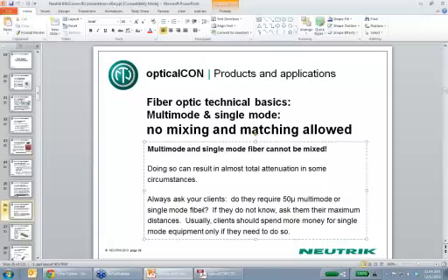Is there any hope of MADI equipment migrating from multimode to single mode in the future? Oh, this is a great question. All right, so let me talk quickly about MADI. This question came from an audio person. The multi-channel audio digital interface standard can run over either CAT cabling, like Cat5, or can run over fiber. And the standard is 64 bidirectional channels, 48K.